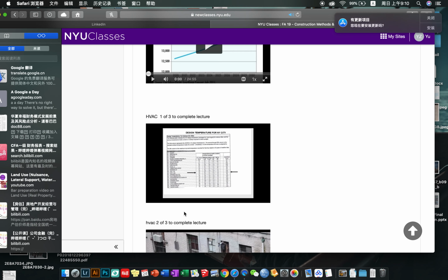And just for an example here, we see that the average temperatures that we design for on the high end are about 91 if you look at New York, even though we can get a maximum of 100 or more on a very hot day here in New York City. We know that we have that diversity factor, right? We don't have to design for the highest possible temperature, because it's rare that it ever gets to that. All the worst case scenarios are very rare. So we can design to something lower.